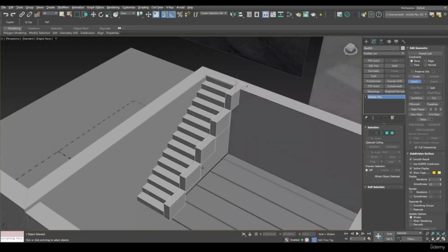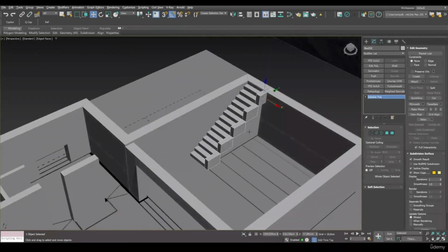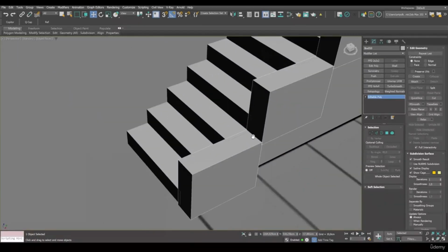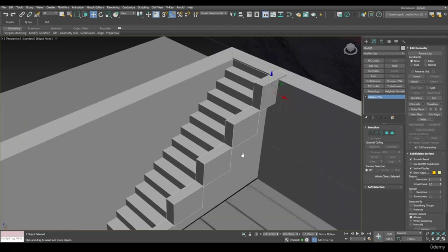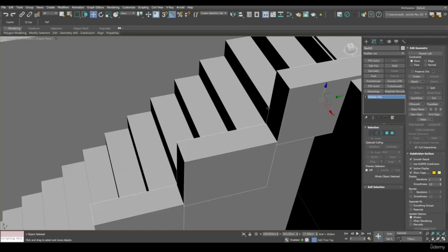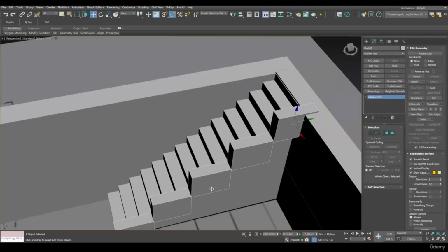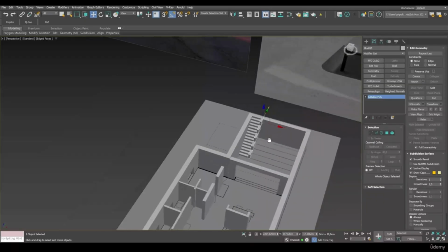We made these concrete blocks, attach them into a single mesh, move them closer. We can raise them a little bit to avoid coplanar here, so there aren't any intersections of polygons. I'll raise them like this so that there are no front intersections in these spots. I will move it forward. This is done for future convenience.